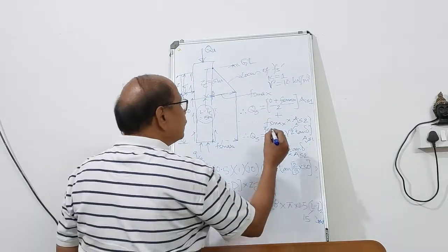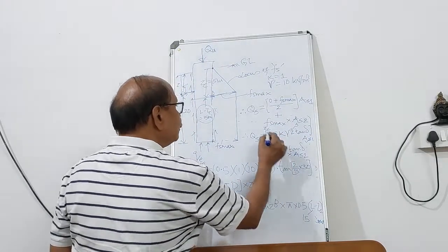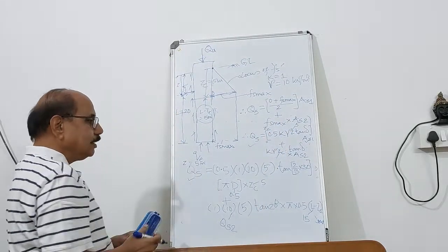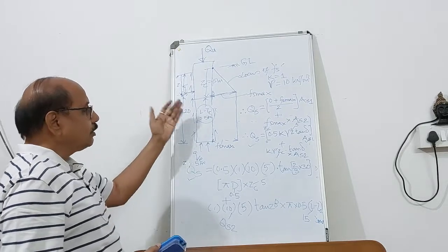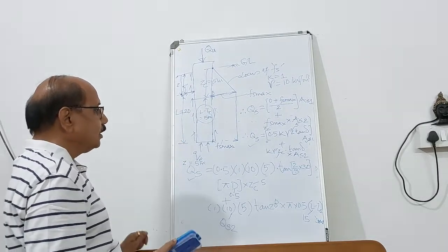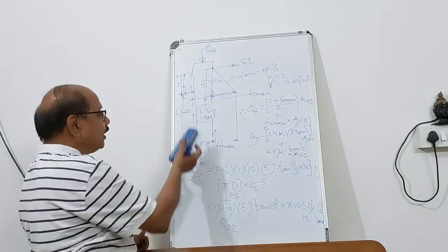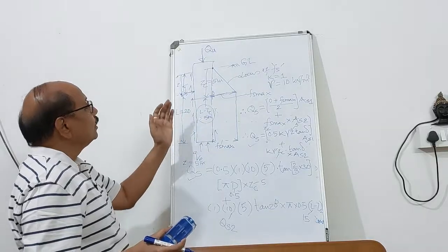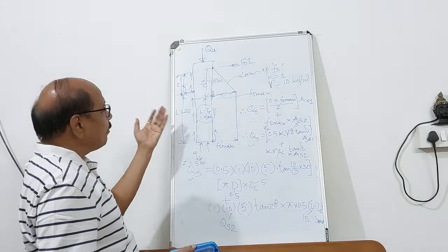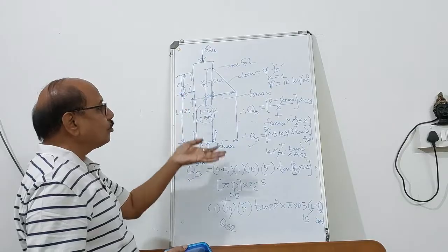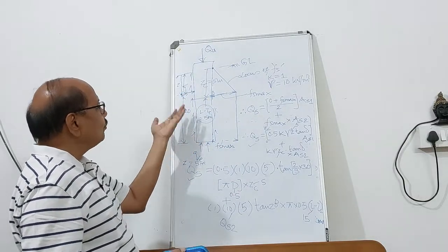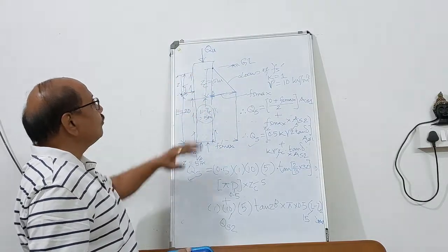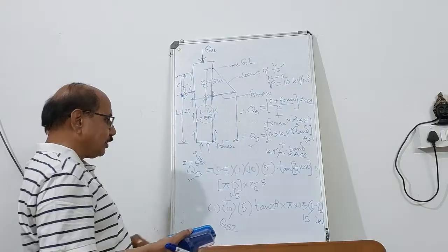So this is the way you can compute the total skin friction. We have tried to make you understand with the help of this. So you can't use the property of the cohesive bed. Here it is non-cohesive, therefore C will be 0. Phi has to be taken into consideration, and this is how the unit skin friction can be calculated.